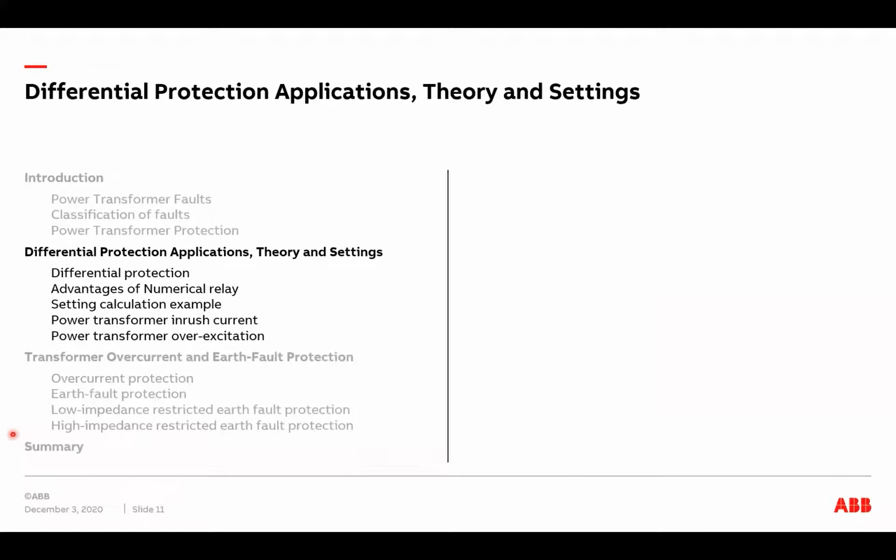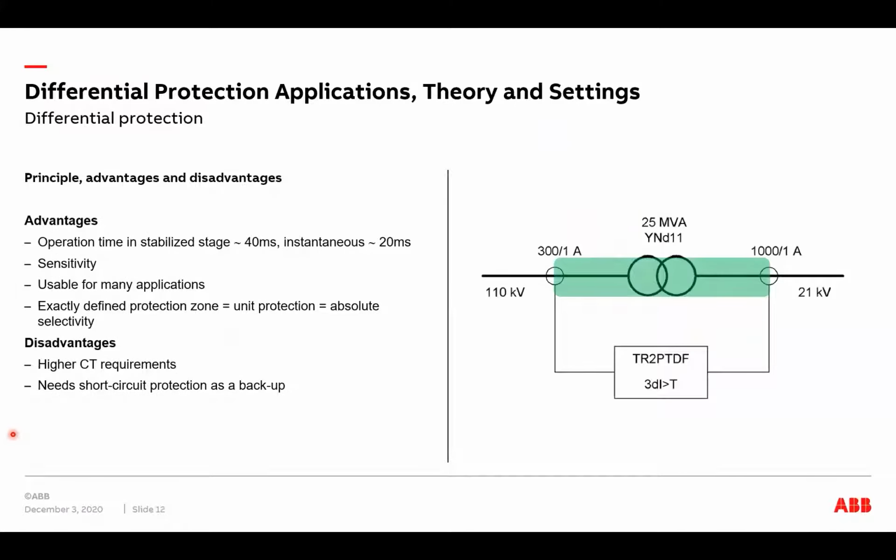So let's then have a closer look at the differential protection for power transformers. First of all, we will look here at some advantages of the differential protection. So the differential protection consists of a stabilized stage and an instantaneous stage.